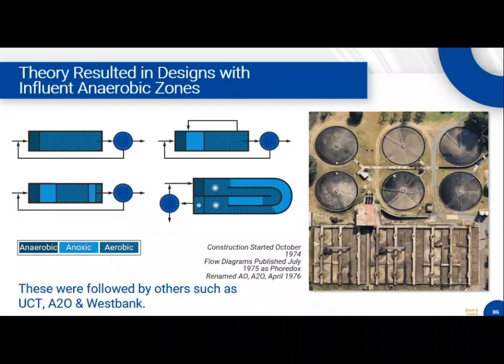So what you see at Cruise is there's a lot of sampling that goes on to characterize the influent BOD and COD, right? RBC, like flocculated and filtered COD, soluble COD. You get these requests from me and Eric, like, can you do more of this data? Well, this is why it's important, because that carbon fractionation, the type of VFA you have coming in, really determines how you need to operate your wastewater plant to hit effluent phosphorus numbers. So it all trickles around: understanding your wastewater characteristics is what really determines how you implement BioP and how stable performance is going to be.